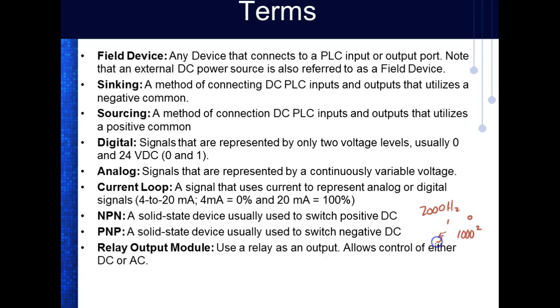If I use the 1 bit, it'd be running at 500 hertz. If I use the 2 bit, it would be running at 250 hertz, because you get a power of 2 every time. Your first bit is what we call a divide by 2. Then it goes divide by 4, divide by 8, divide by 16, divide by 32. You don't want to use this one because if your light was flashing at 1,000 hertz, it would look on all the time. These lights are flashing at 120 times a second, and to us they look like they're on all the time. So you'd use one of these upper bits, and when you bring up that output register, you can actually see which one you want to use.